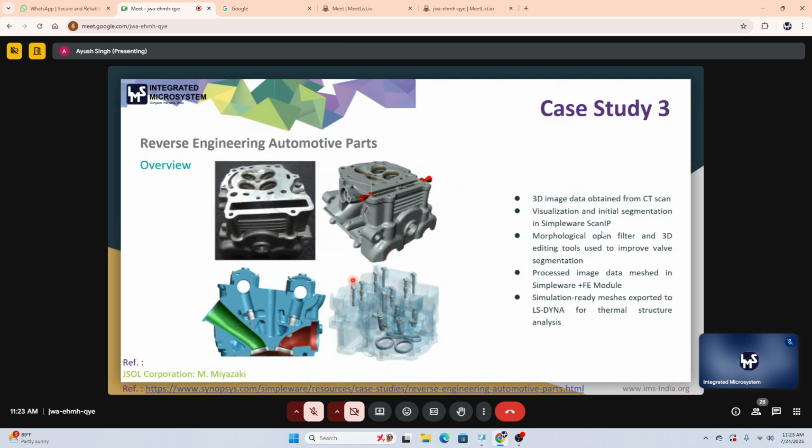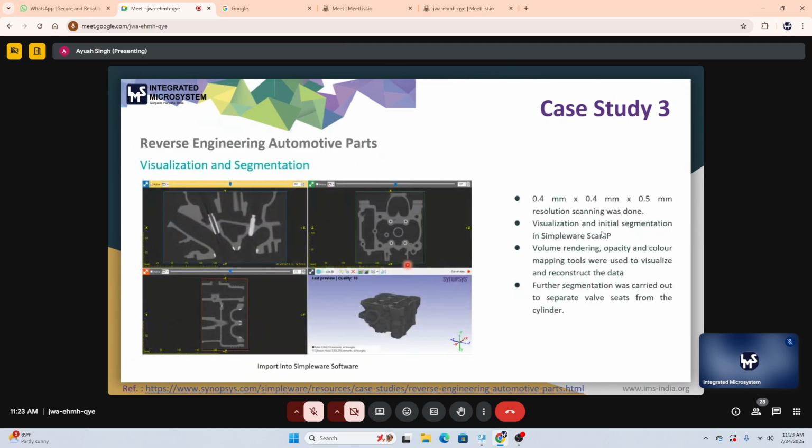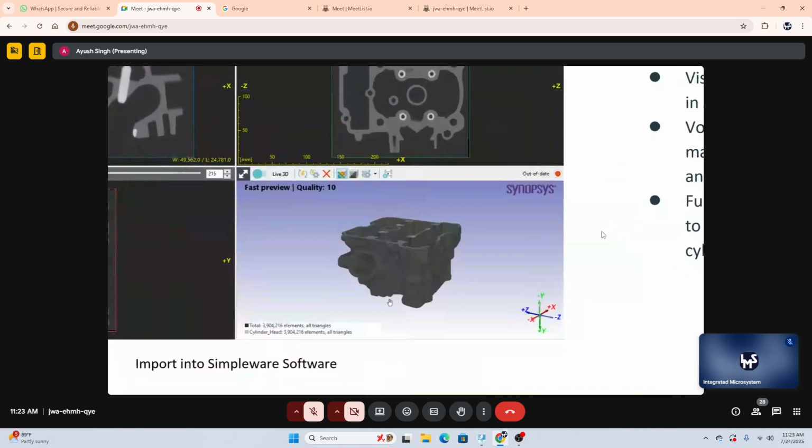It was generally done to check the placing and fittings inside the particular engine intake, and once the placing and fittings were placed, the particular model was generated, a finite element model was generated, and again the finite element analysis was conducted. So how the particular process went through, we have taken the engine intake in a simple way. You can see the placeholder and fittings over here. So we have the placeholder corresponding to which the fittings were done. This is the engine intake in the 3D view.